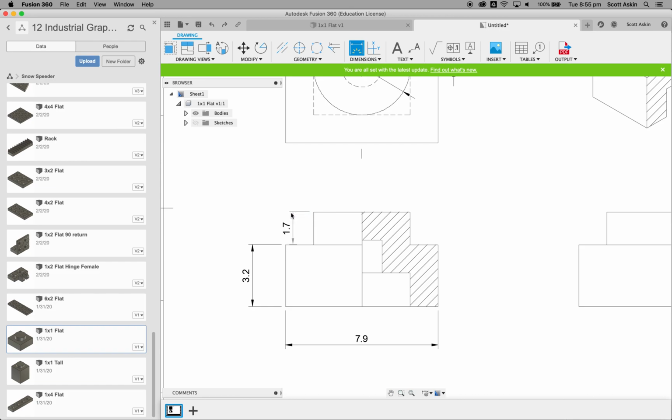And then drag out. And can you see the difference now in that we've got a gap here and a gap here, which is correct. So the rule is that the leader line, which is the line that's like an extension of the outline, must always have that small gap between the outline and the leader line. It helps to distinguish between the two of them.